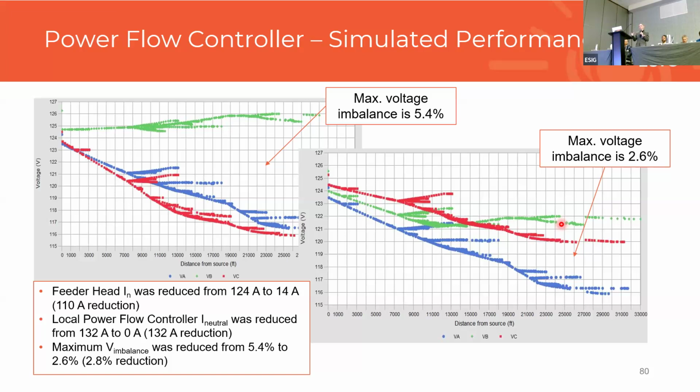What that ended up doing was it left B phase largely untouched. And because it left it largely untouched, it didn't really resolve the limiting, what would have been a loading condition on B phase. So if you added more load on B phase, you would have gotten more voltage drop. You would have still run up against that one, but it really helped your high voltage limit there.